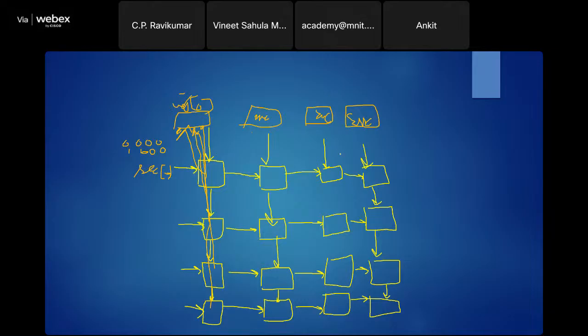It's expensive because we are doing so many things. We have 16 comparators, and we have four of these encoders. So maybe it's a little bit expensive in area. But then it is going to do it combinationally. We don't need to have the hassle of designing a controller and all that kind of stuff. You may have other designs. This is not the only way. I'm just giving you one possibility. You could do it in so many ways.